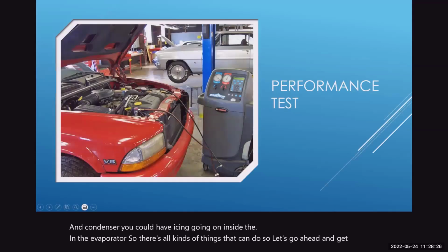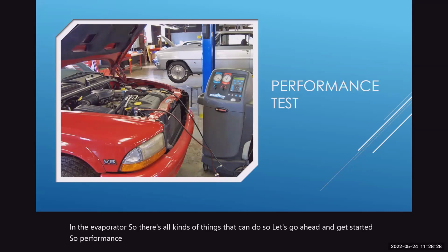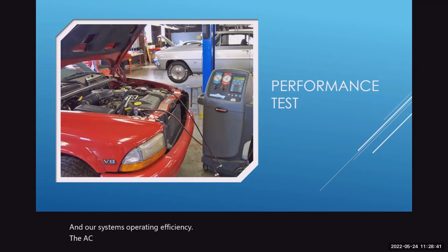Performance testing provides information about the AC system's operating efficiency. The AC system high side and low side pressures are measured, and the discharge temperature of the passenger compartment is measured.